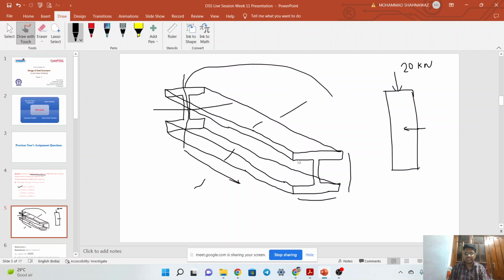Yes, sir. So now see here. What will happen here, when you have fixed the length of your beam? Now you just start reducing its cross sectional area. At one time, in its weaker plane, your beam will buckle. Initially, with this cross section and this much length, it was not buckling. But later on, when you fix its length and just reduce its cross sectional dimensions, meaning you reduce the flange thickness or the web thickness, at some point at the same load this section will buckle. Why will it buckle? Because the slenderness ratio depends on its length and its cross sectional dimension. So that is why it will start to buckle.